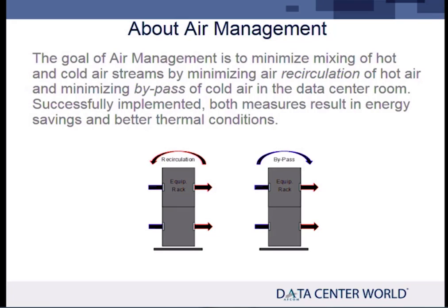The other one that I wanted to point out here is rack recirculation. This is in the case where you don't have enough air. So in the case where you've got a 10 kW rack and you don't have enough perf tiles in front of it or whatever, it's not getting enough air, it's going to inhale its own exhaust. It's going to go right around a circle. Air is very lazy. Question? Yeah, you have to use some kind of air management system. Yes. Now, whether it's containment or whether it's aisle separation or whatever, there are many different techniques for doing that.